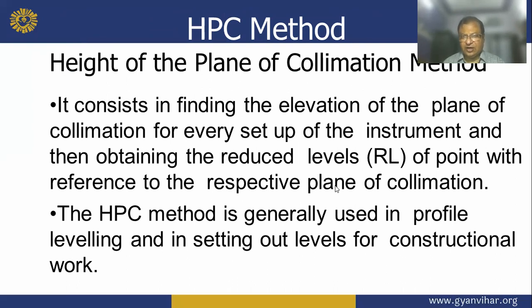Now, the height of the plane of collimation method consists in finding the elevation of the plane of collimation for every setup of the instrument and obtaining the reduced level of a point with reference to the respective plane of collimation. The HPC method is generally used in profile leveling and in setting out levels for constructional work.